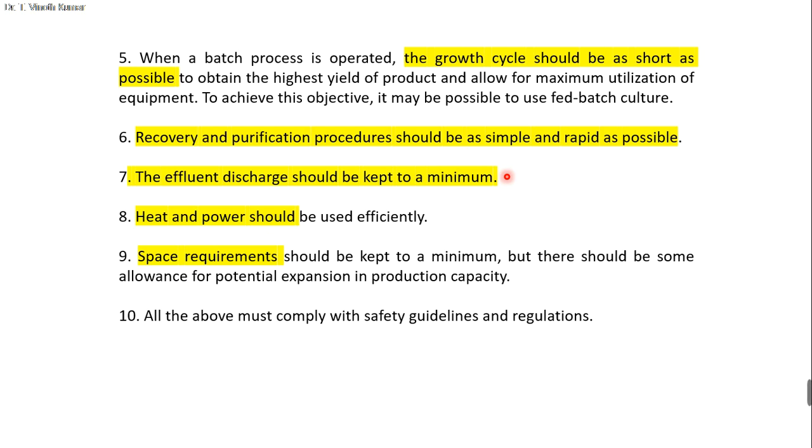You can have an alternate power supply, because in India reliable power supply is required. You should always have an alternative power supply, and 24/7 power supply is required. It is not for waiting 1 hour, 2 hours to resume the power. It is not like that. The fermenter and everything will be clogged, including the sparger, all the pores will be deposited with the microorganisms, and the sparger will be clogged. The heat and power should be used efficiently.